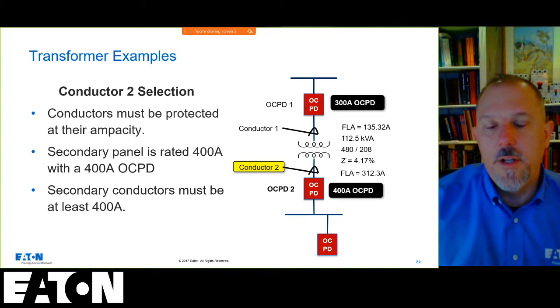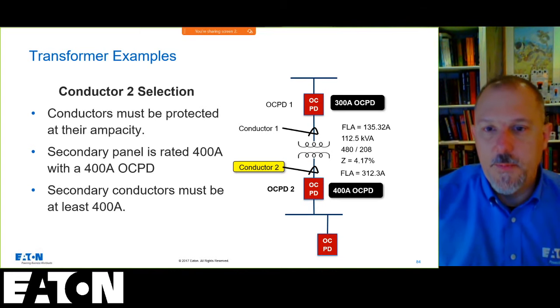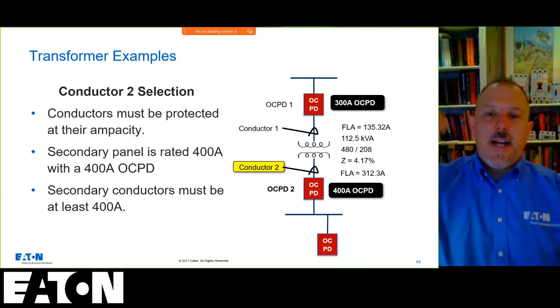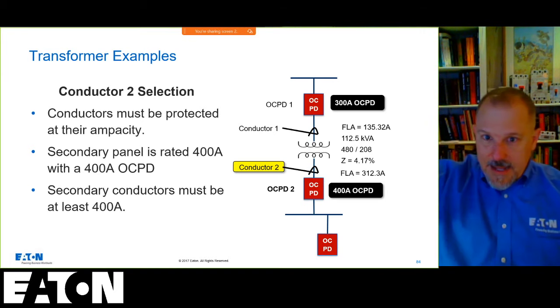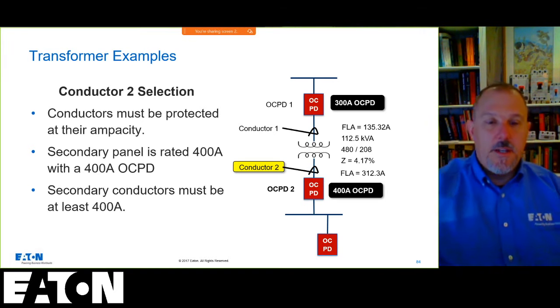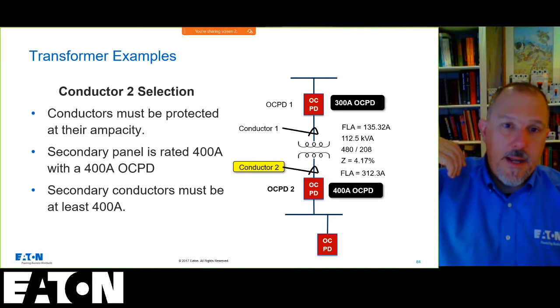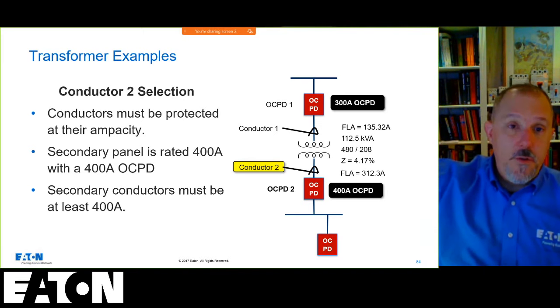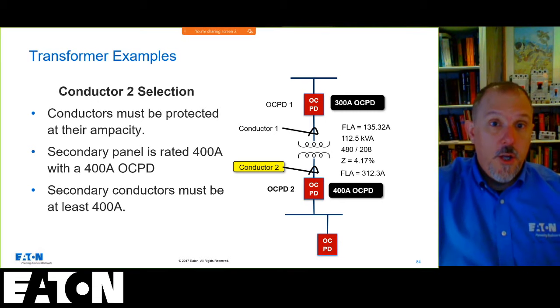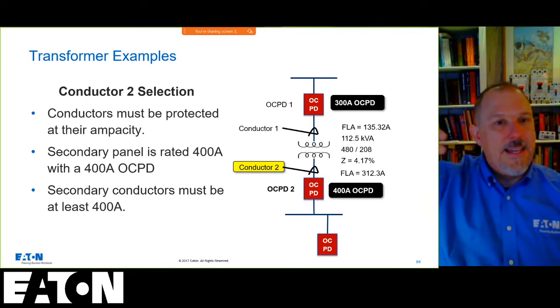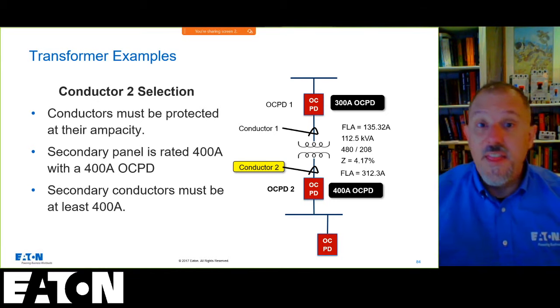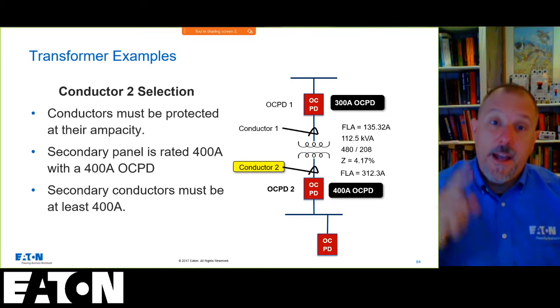NEC section 240. So the point being made in our chat session here is that I could size that primary conductor, I can bring that down to 175%. I can put, like I showed you on that fuse, something even smaller. The maximum number, that 300 amps, I can't go greater. I can go anything smaller that will let that transformer energize.